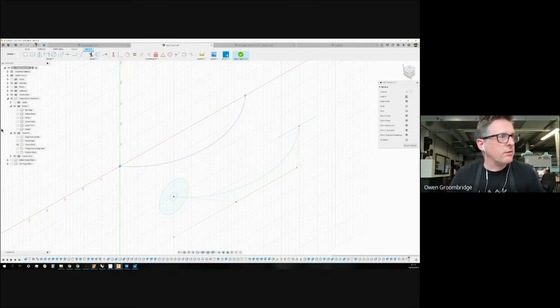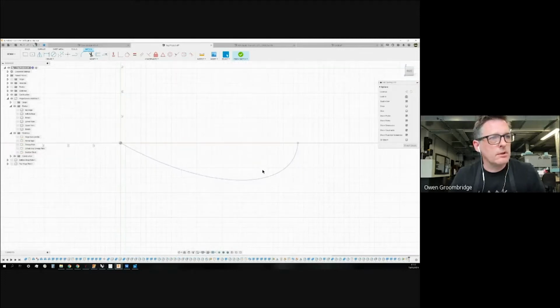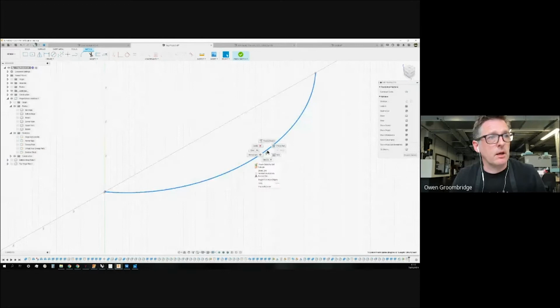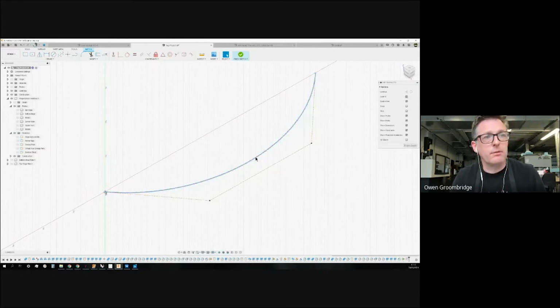Also, you might notice if I turn that sweep path off, if I hover over that, there's a little symbol that appears, of a cube and what looks like a surface with a square in it. That's the symbol for projection. All right. So I could select that, and if I go to break link, sure enough, that's no longer purple, it's gone to blue.